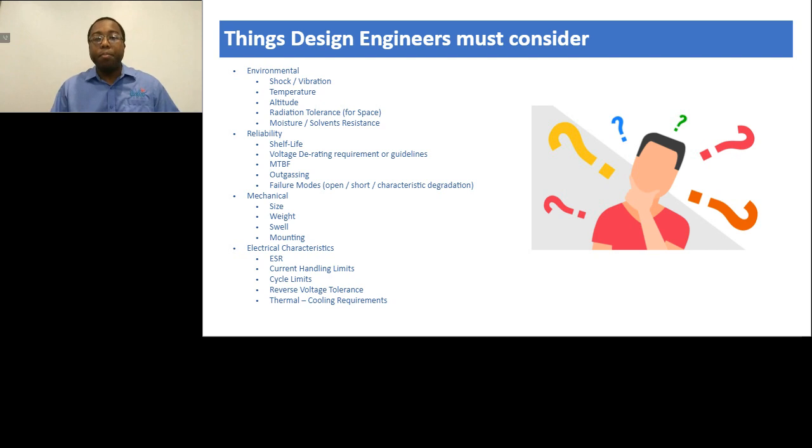A capacitor's electrical performance will contribute to overall system efficiency. Capacitors with high ESR can generate more heat and contribute to voltage droop. Understanding current handling limitations and cycle limits will have a large impact on how the system is designed.